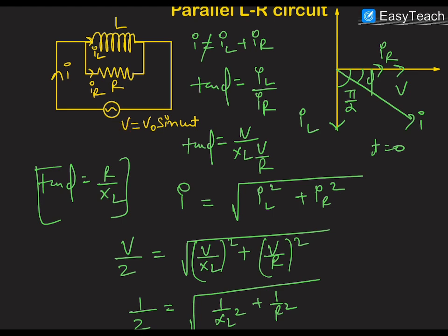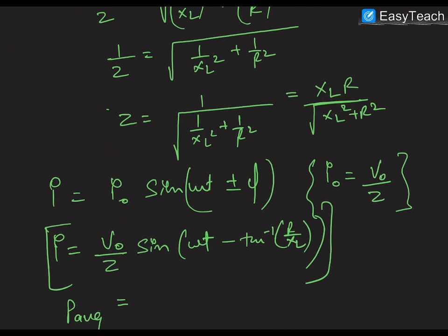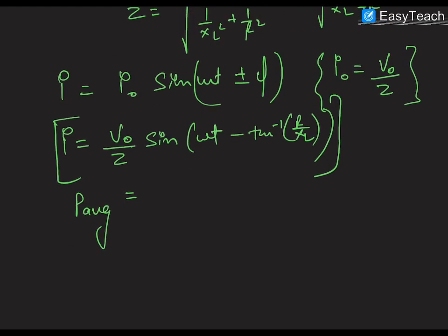We also know that the element which does the power loss is resistance. So we can directly write the average power loss as Vrms square by R, because VR, the voltage across resistance, is equal to Vrms, the net RMS voltage. And obviously we are talking about the RMS voltage because we always associate power with RMS voltage only.